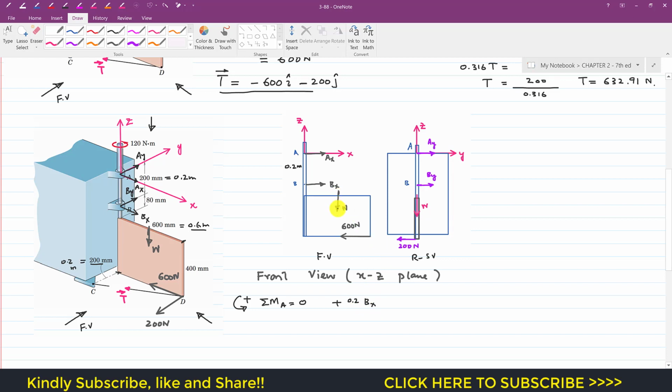Similarly, this weight is going to produce a clockwise moment about point A, so I will write minus, the weight is 15 times 9.81, and the perpendicular distance of this weight from point A is this distance, and from here we can say that this distance is 300 mm.